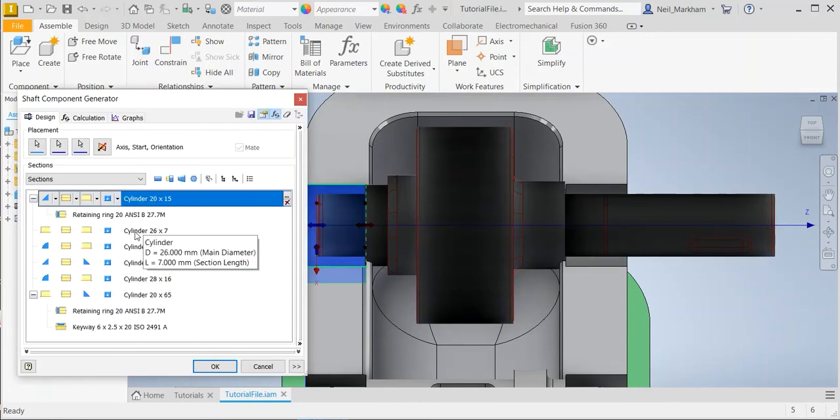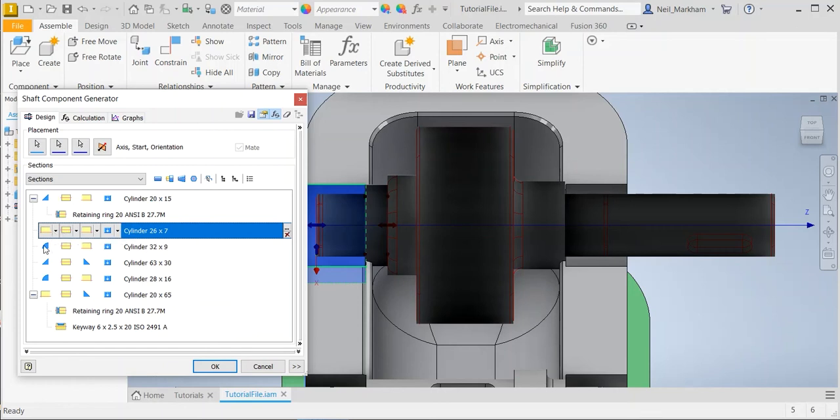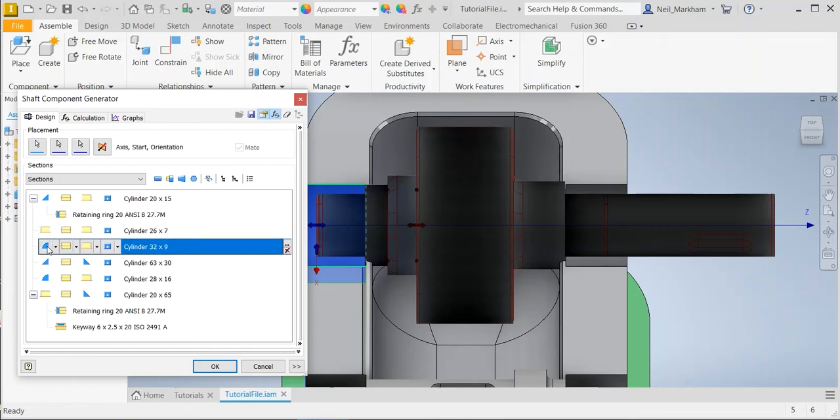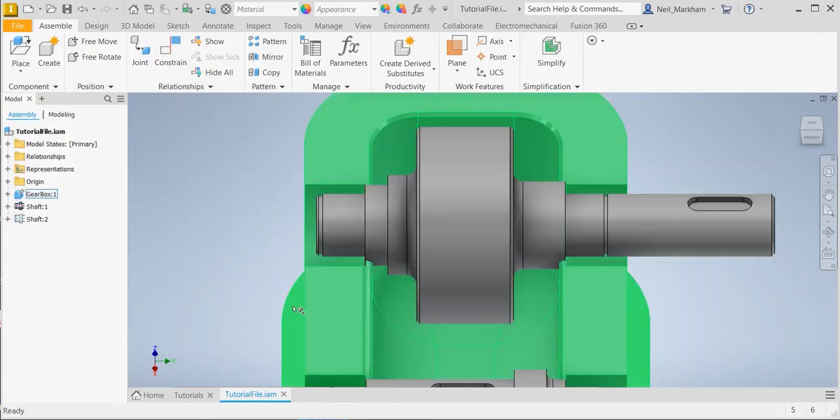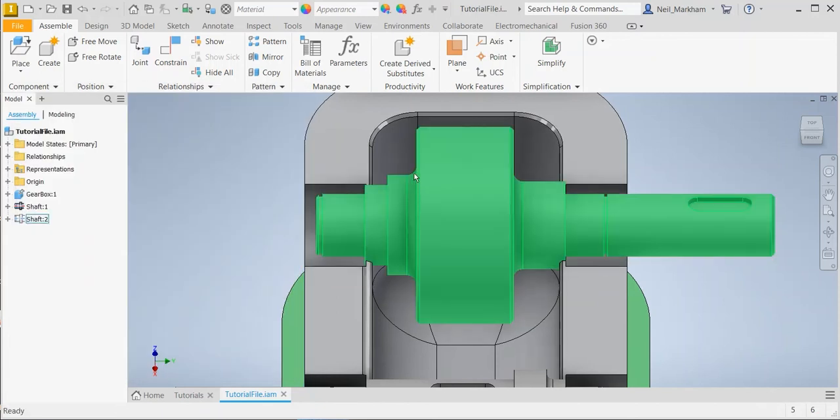And for that cylinder where there's a fillet, I'll change that back to no feature for the moment. I think I should have put the feature on the back edge. So we'll add a fillet here, a value of 3. OK that, and OK that. So that fillet there is much better. So we've got a chamfer there, a fillet there, chamfer, chamfer, fillet, and then a chamfer at the other end.